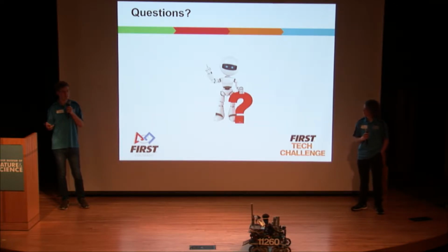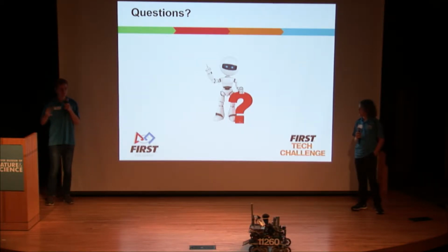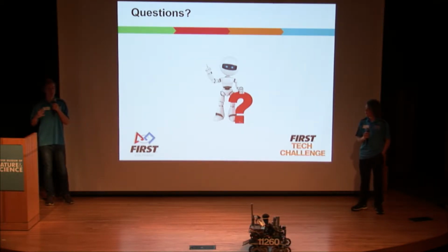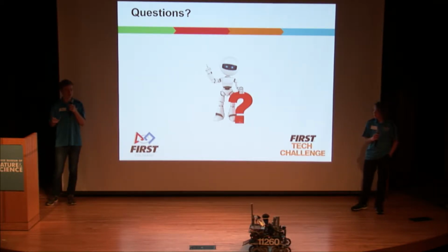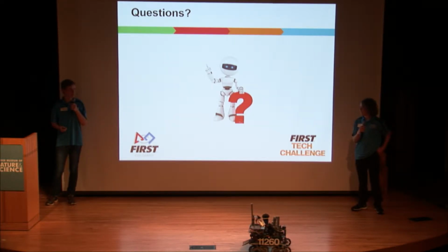So most often, the standard wheels are a combination of the traction wheels with just a rubber outer layer all around them, and the omni wheels, which allow for a much easier and better turning radius for your robot. So those are the common ones you'll see on standard tank drives, and those are the ones we used last year.